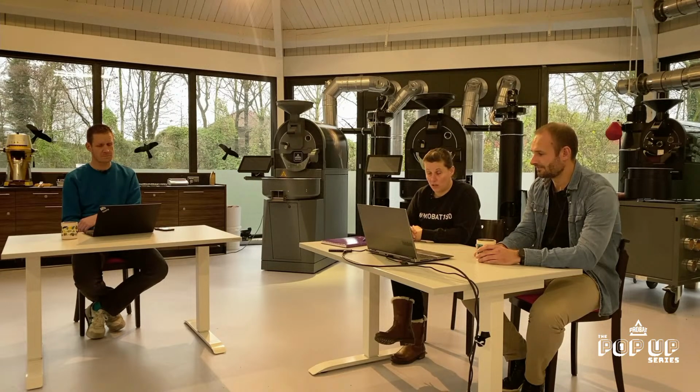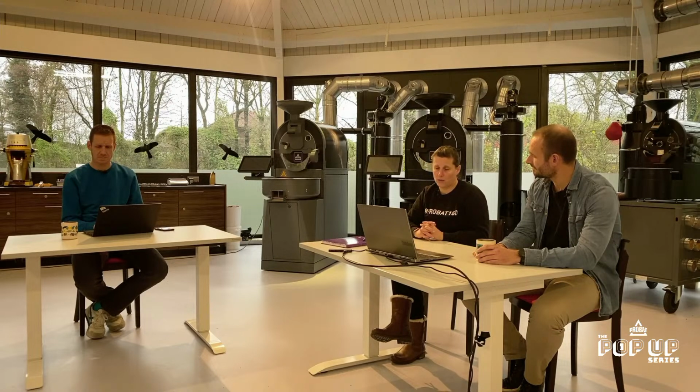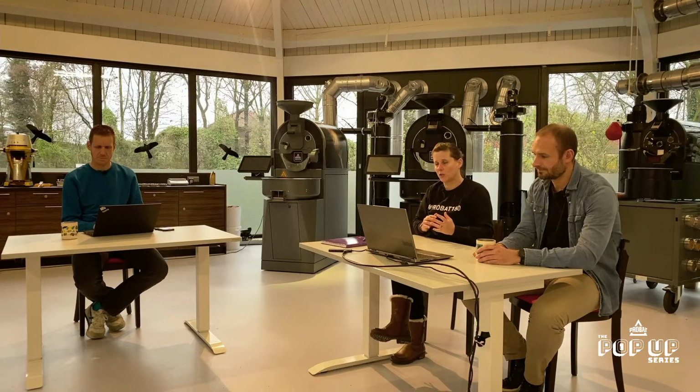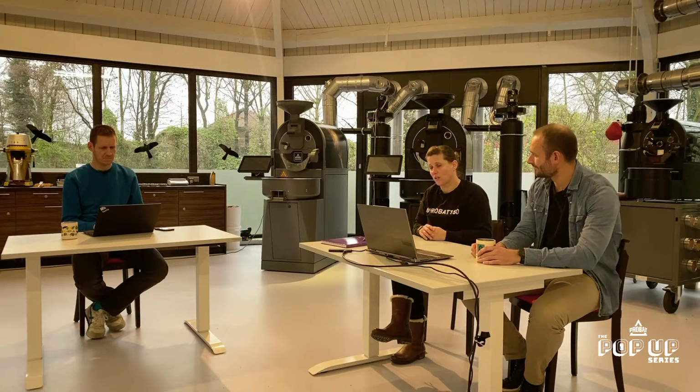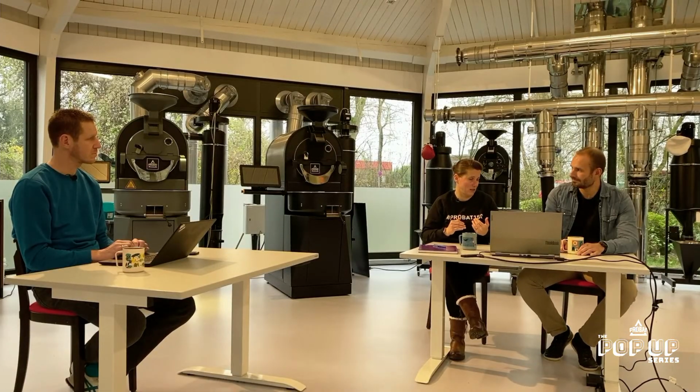But this has changed a lot, because what are we doing today? The software is not only just following the steps of the burner, of the heating, but it's looking for the temperature of the product. So according to the temperature of the coffee, the temperature of the air in the room, the pressure that we're having in the system, the burner now is realizing, do we need more or less power, and it's adapting by itself. And I think this is a super cool feature.